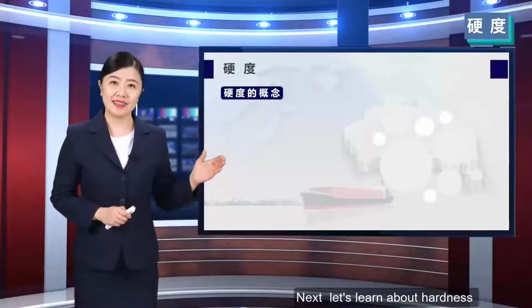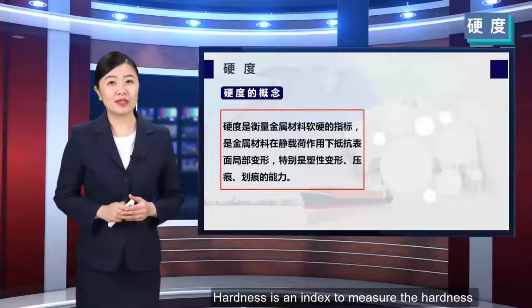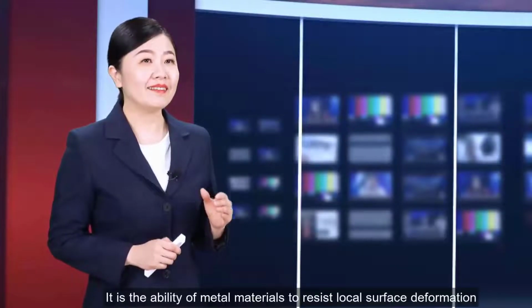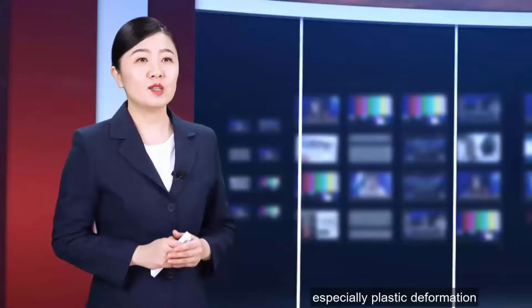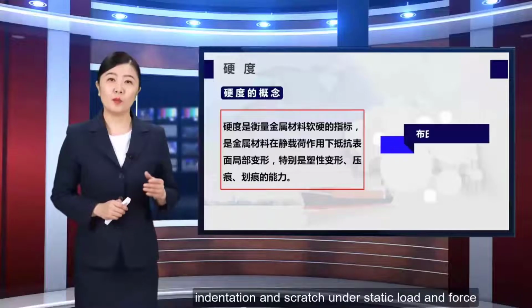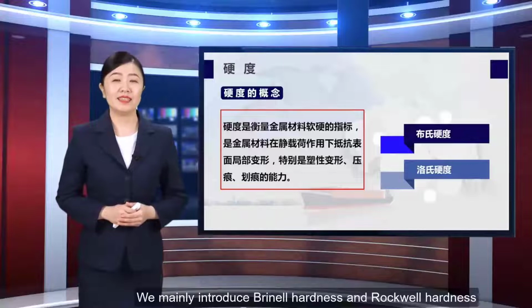Next, let's learn about hardness. Hardness is an index to measure the hardness and softness of metal materials. It is the ability of metal materials to resist local surface deformation, especially plastic deformation, indentation and scratch under static load and force. We mainly introduce Brinell hardness and Rockwell hardness.